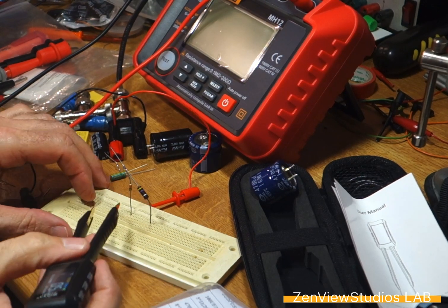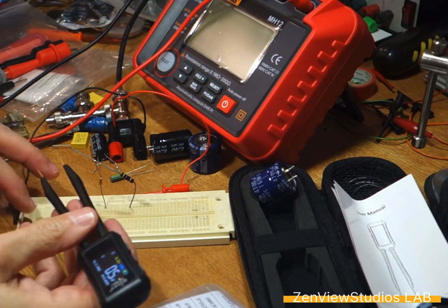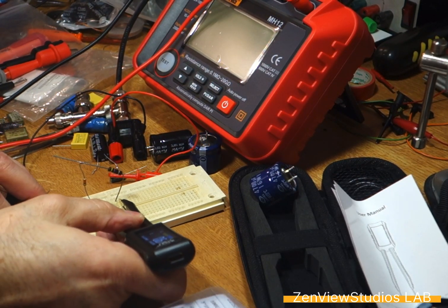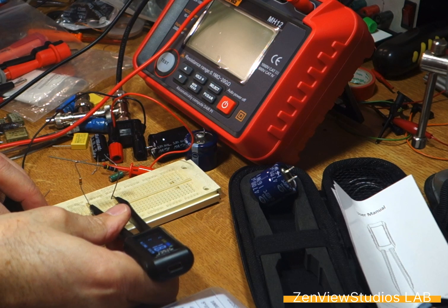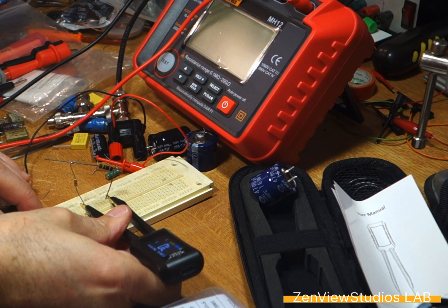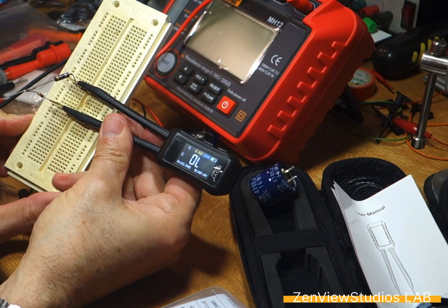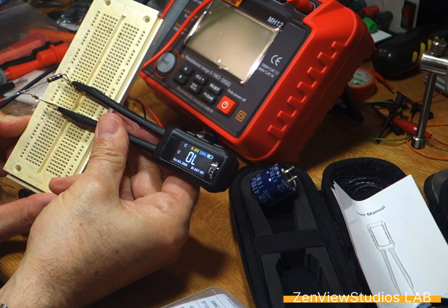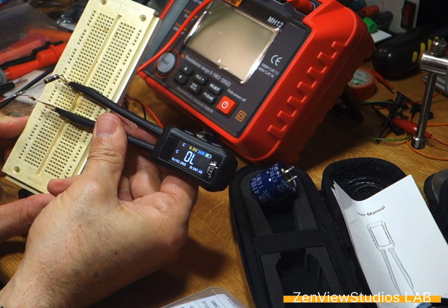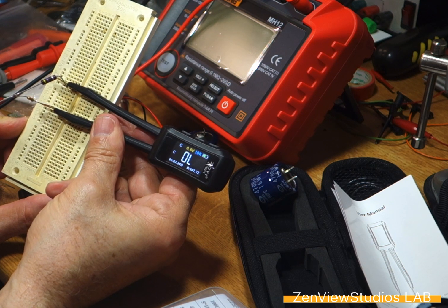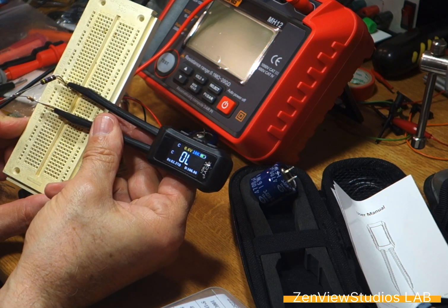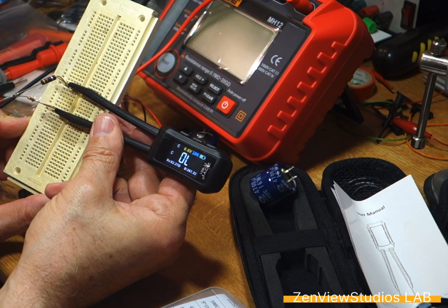This is also true if you measure in capacitance mode ESR, because you can see here the value that's shown, 82.2928 for the ESR value. What I'm saying is that one way to check an ESR meter is just to put a resistor.